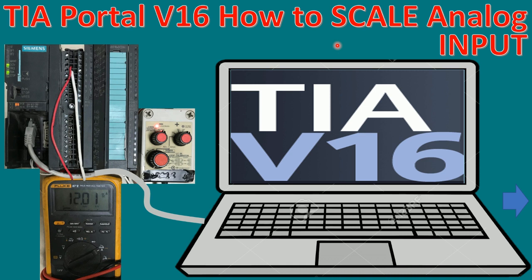First, we need to have the current loop calibrator or current loop source, and we connect it in series with the milliamp meter to measure the milliamps sourced from the standard source to the module.